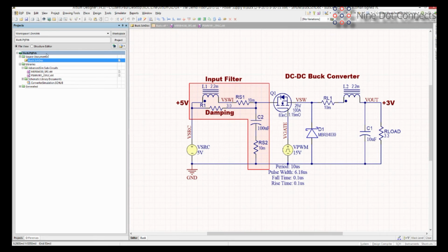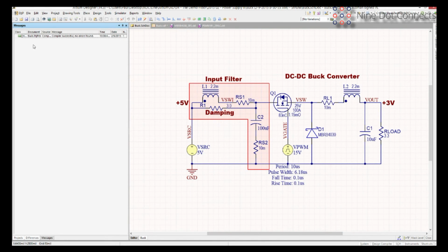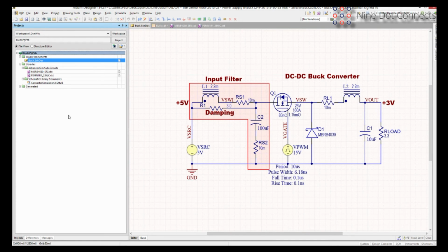And now I'm going to do a compile on it. So I'm going to right click and compile it. Okay, make sure we're all good to go. Because a lot of times it could be syntactical. I want to make sure we separate those things that are SPICE related versus those things that are just simply an ERC issue that we may have. So if I go under System and take a look at Messages, and I bring it up, everything looks hunky-dory at this point. And I am going to leave this Messages panel up here because in a minute I'm going to run the SPICE simulation. You're going to see a few other errors that are going to appear here.